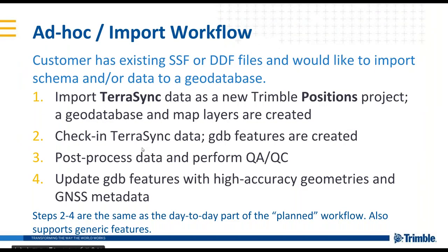So the second workflow that I want to talk about is kind of this ad hoc or import workflow. So this would be a case where you have an existing SSF or DDF file. Okay, this is data you've already collected. Maybe it includes generic features. It's based on your own data dictionaries you've already used, or it is a data dictionary you've already set up, and you'd like to import that very quickly and easily into a geodatabase, get those sessions in, work with them. Optionally, I want to be able to get that schema in such that I can maybe create a different type of project. I want to bring a schema in from an SSF or DDF and then use it for a TerraFlex project or use it for an ArcPad project.